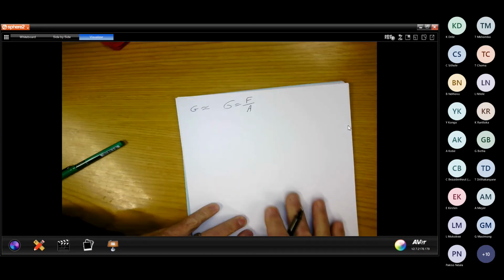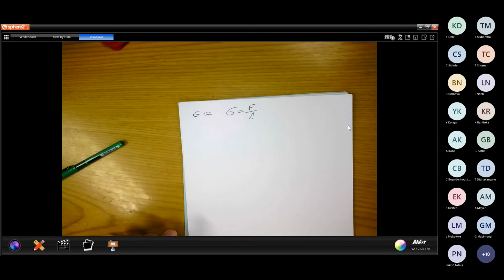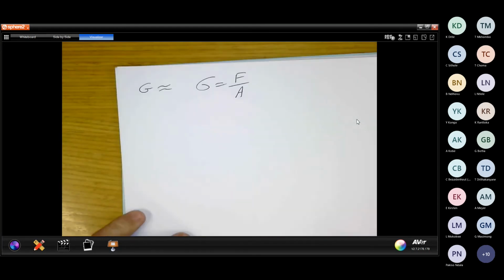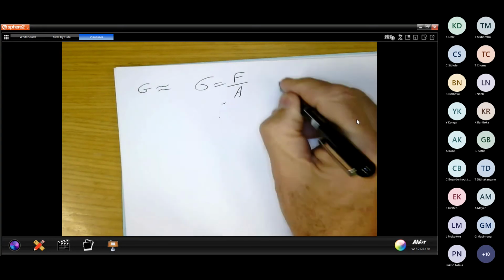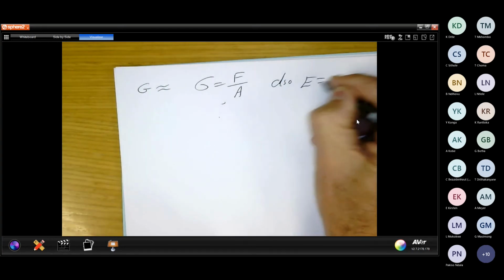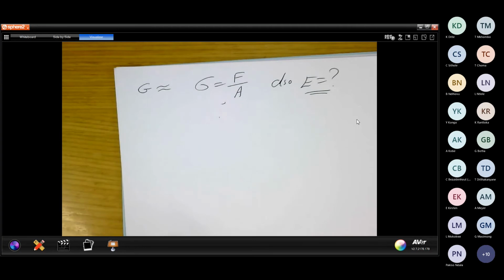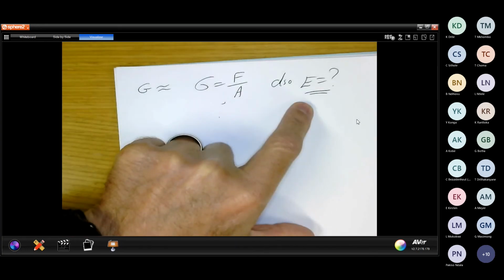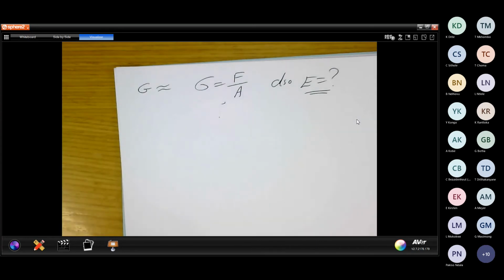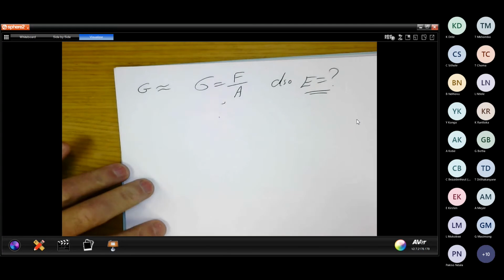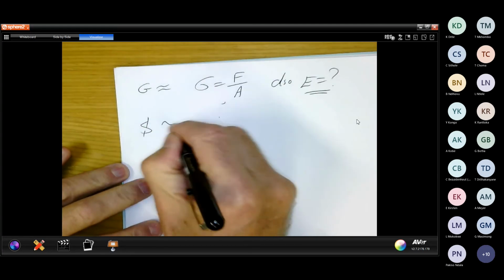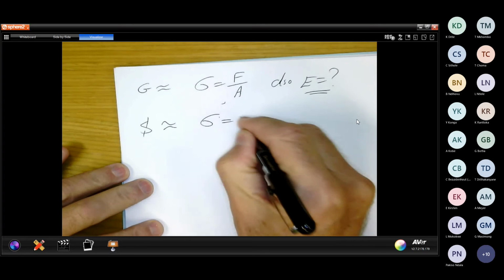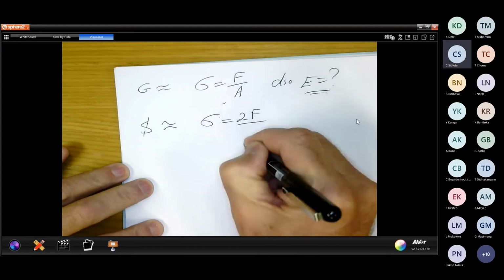Inverse, make it a little bit bigger for you guys. Inverse here, can I also calculate Young's modulus if it's not given in the question? I can still use the gradually applied load to calculate Young's modulus, because we are in the first part of my stress-strain graph. The next one is suddenly applied, where we know the force is 2 times force over area.